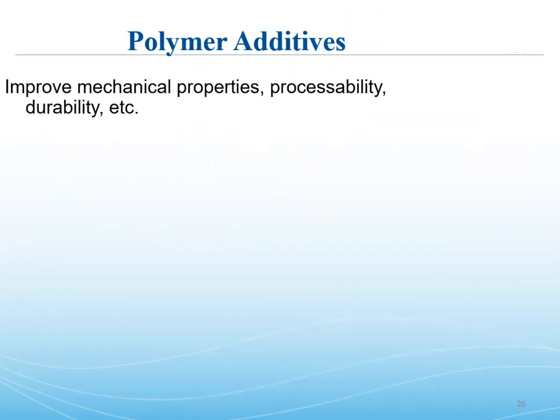Additives. Very few polymers are used neat. This is independent of a deliberate composite. Even pure polymers, quote unquote, aren't ever typically very pure. Polymer additives are deliberately added to improve mechanical properties, mainly processability and durability. For the most part, the ones that are added to improve processability actually detract from mechanical properties in terms of strength. So you have fillers, which would be an exception to what I just said.